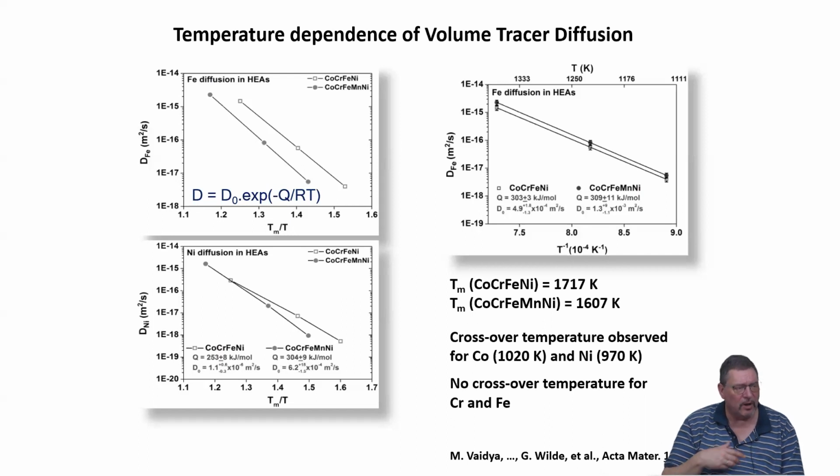And if you would now, even in conventional alloying, add an additional alloying element with substantial concentration, you would also expect that diffusivity goes down on the same order of magnitude, less than 1 order of magnitude at given homologous temperature.